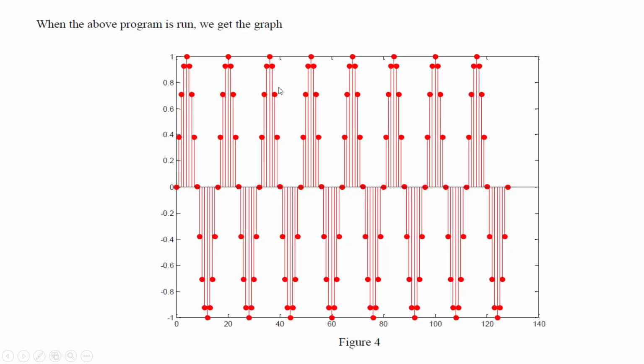that means you will get 16 samples in one period. So if you count from this point to this point, you will see that there are 16 samples. This particular zero value will belong to the next cycle. Up till this point this will be counted, and starting from this zero up till here, this will be counted as your 16 samples. So that means in one period you will get 16.